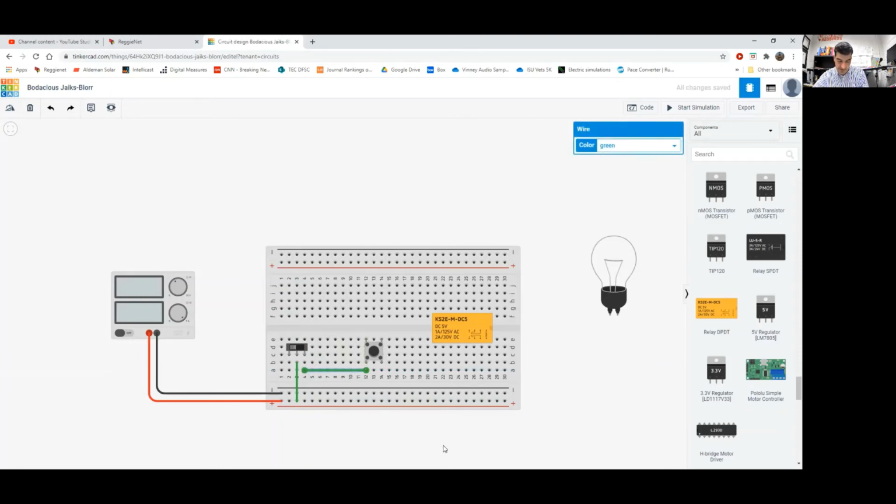But look, right below that, there is another wire. It needs to go from the output of the stop push button, so one of these connections right here. And it needs to go to the common, that's the input, of CR1A1. So that's a normally open contact, but we got to use the common. That's the input for the contact. So we got to go from here, and we got to go to the common.